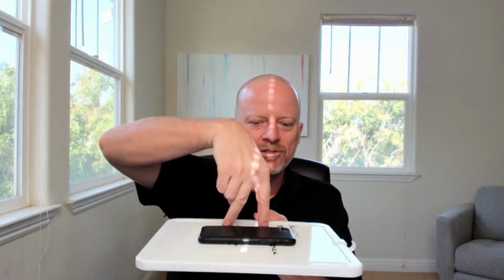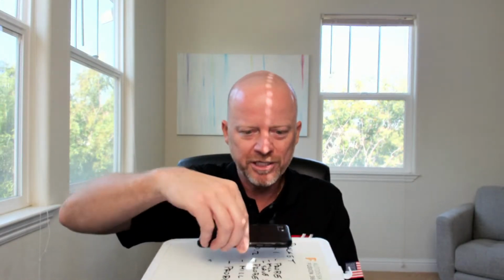I just thought about that. So, going back, we've got the part in there. I can put a dowel pin in 2 locations and put a pin here. So that way when the operator, or me, drops the part in the machine, you push it against the pins, and then you know the part is in a certain location. So that's how I would probably set it up on my machine. Vise would be different. I would just put it in the vise and push it against the stop.